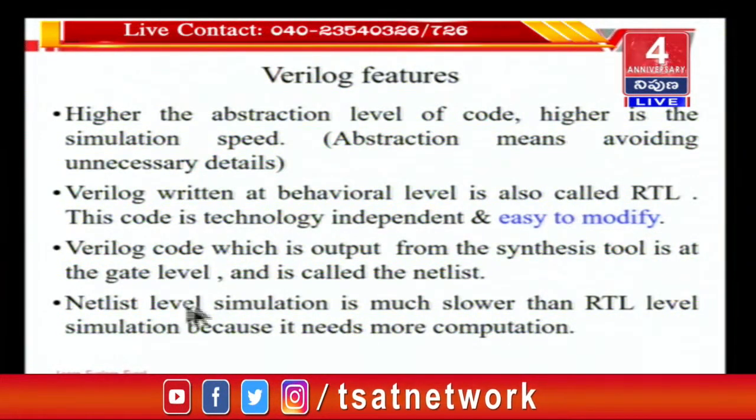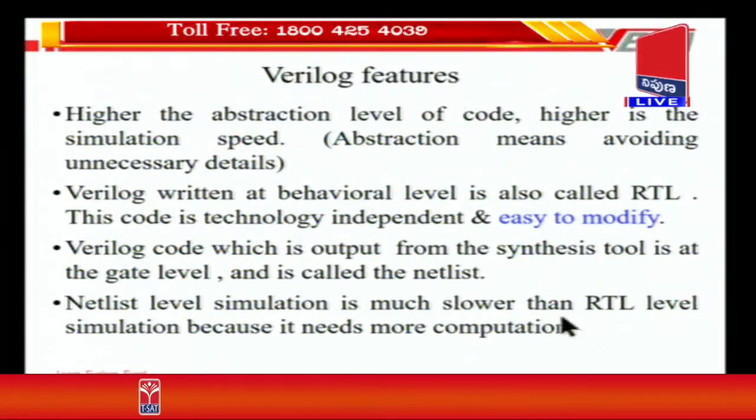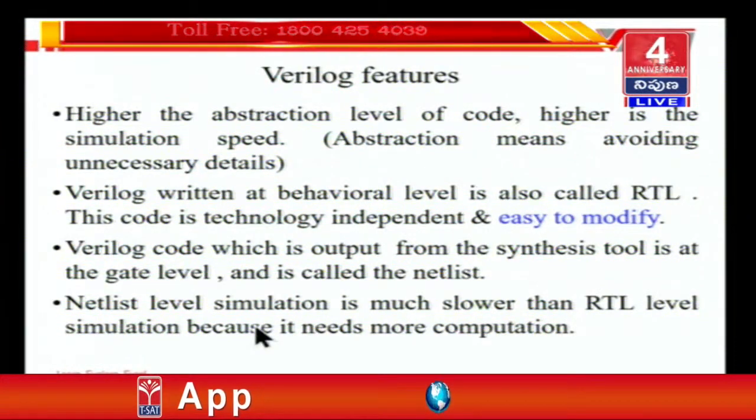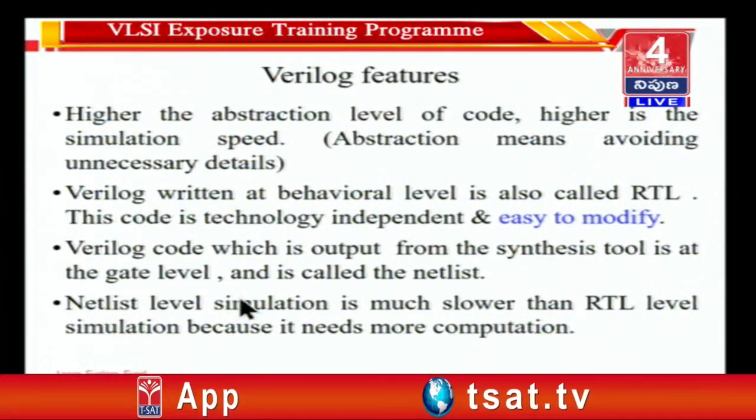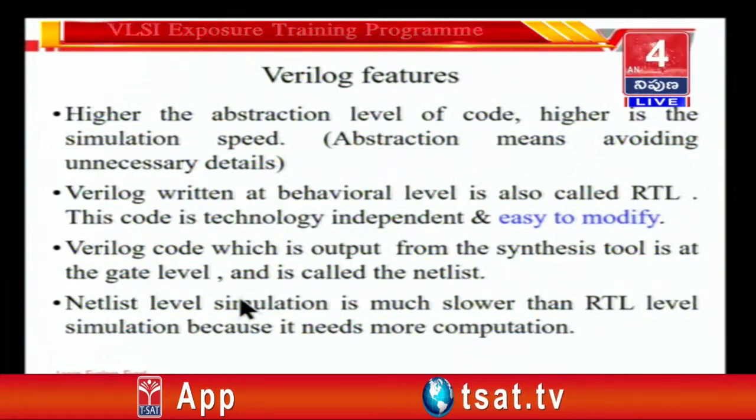Okay. Then netlist level simulation is much slower than RTL level simulation, and therefore RTL level simulation needs to be done extensively in order to verify 100% or maybe 110% of the functionality.